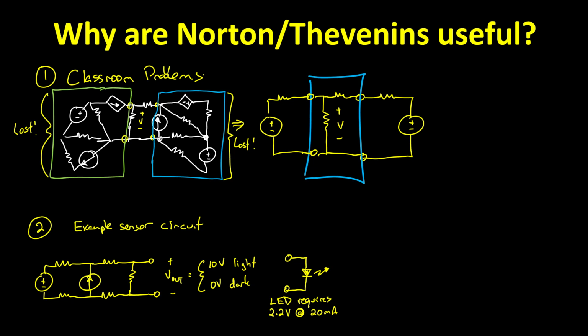At first blush, it seems like it might give too much voltage, and you'd need to cut that voltage down by a resistor, and if so, what resistor value would you use? To answer that question, you'll first find the Thevenin equivalent of that circuit. And the Thevenin equivalent of that circuit might look like this. And now to it, you connect your LED.